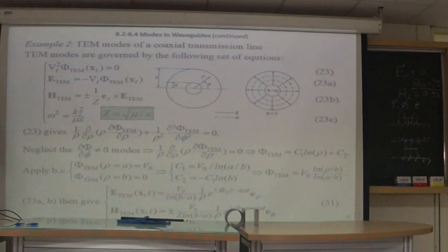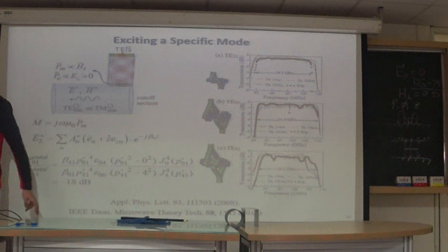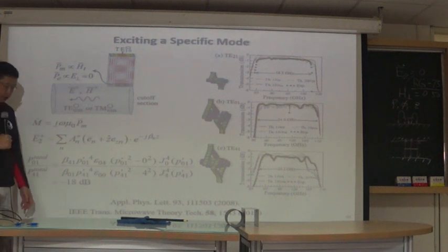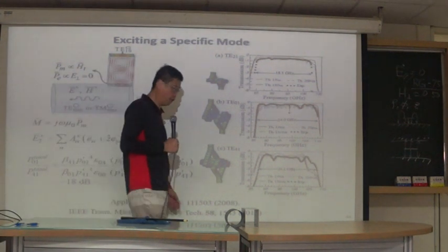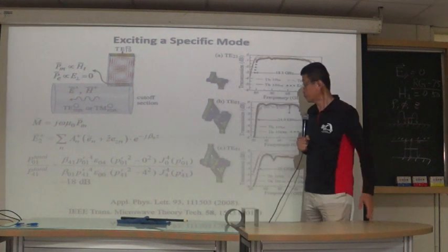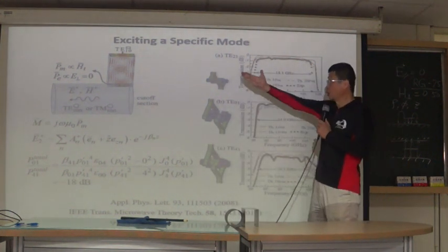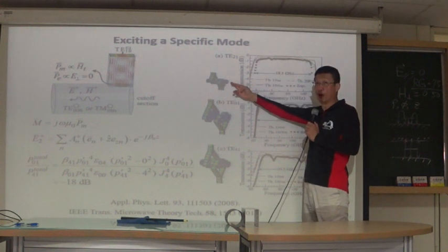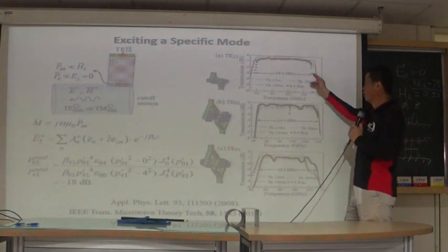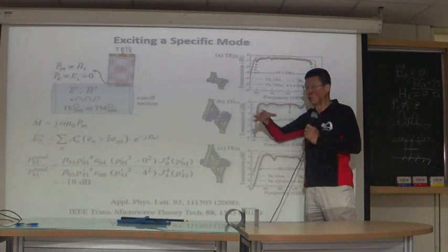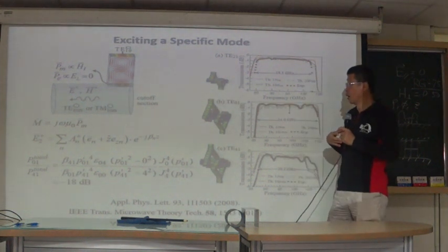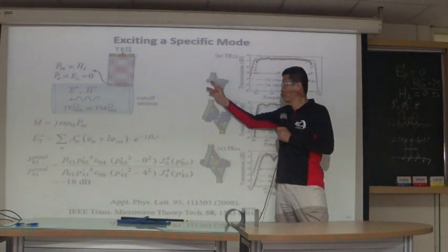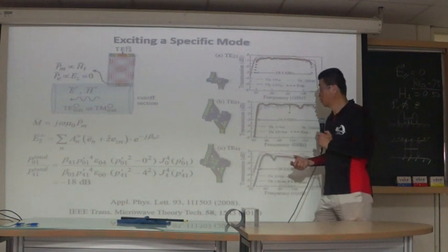Okay, let's move on. Just to give you some idea about the application of the waveguide mode, and how to excite a specific waveguide mode, for example TE21. We can excite it with a waveguide like this one.